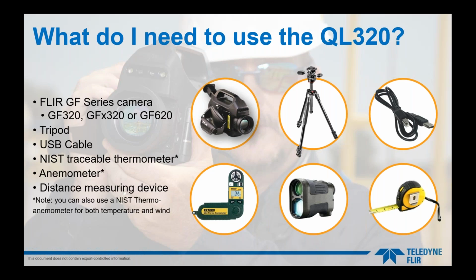So this is movement of the gas, how the gas is propagating through the image, through the atmosphere. So anything that is moving within the image will have an effect on the results. So if the camera is moving around, then that's not really good. We need a stable platform. So a tripod is very, very important for the accuracy of the quantification.